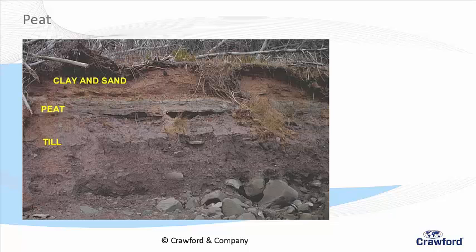So peat, if you do have it, depending upon the banding and how much compression it's gone through, could be a problem. So it's not across the whole country. Particularly East Anglia is one area. There are other pockets of peat around, but East Anglia, Suffolk, I would say out even to the Cambridgeshire area, there's peat. Solution features.